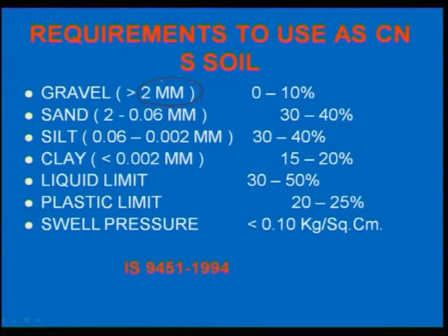Similarly, sand, which varies from 2 mm to 0.06 mm, should be 30 to 40%. Silt also 30 to 40%. Clay, which is less than 0.002 mm, is generally 15 to 20%, and the liquid limit should be in the range of 30 to 50%. Plastic limit in the range of 20 to 25%, and swelling pressure less than 0.10 kg per square centimeter.